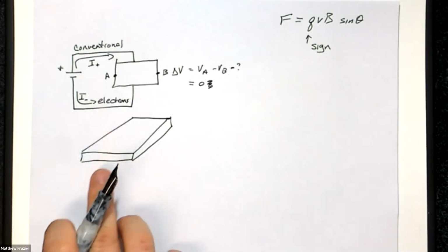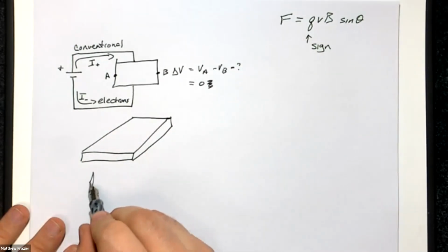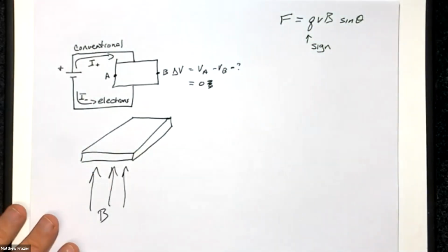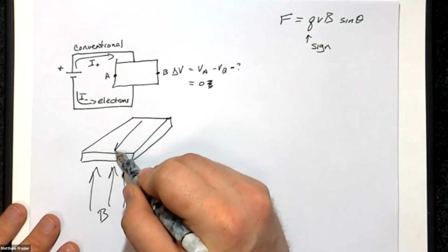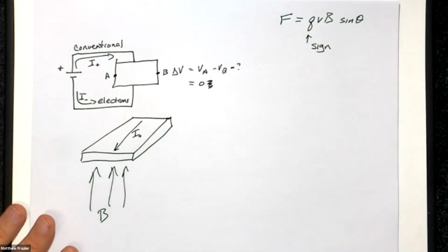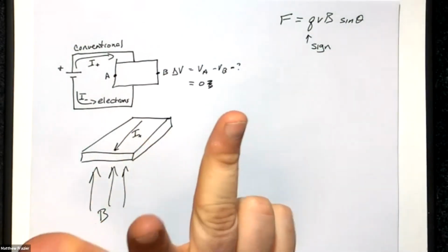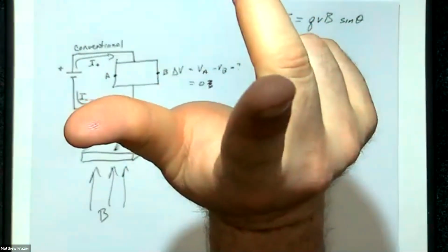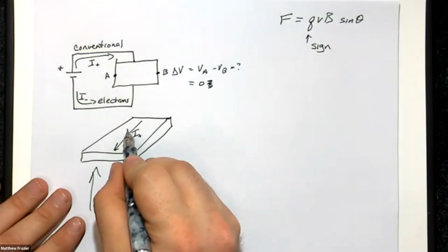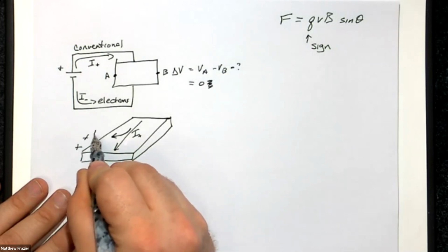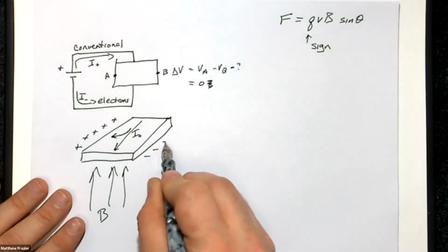Now what we're going to do is put a magnetic field under it. And it's going to go through the material and out. And so if this is our positive current, like this, we can do the right-hand rule to determine what's going to happen to this current. All right, we have the current going down the page or out of the page, and the field is up. And so a positive charge will go to the right. So what should happen is this current should veer off to one side, which means this side will get a positive charge and this side will get a negative charge.